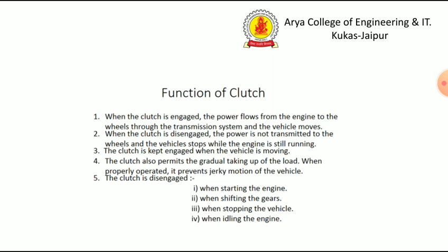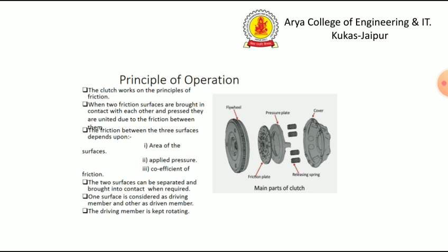And the clutch is disengaged when starting the engine, when shifting the gears, when stopping the vehicle, and when idling the engine. So these are the four times when we will disengage the clutch.